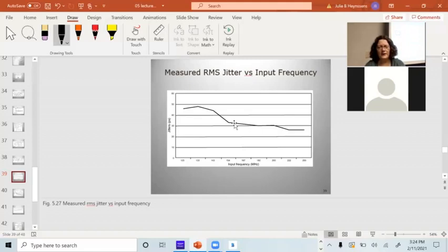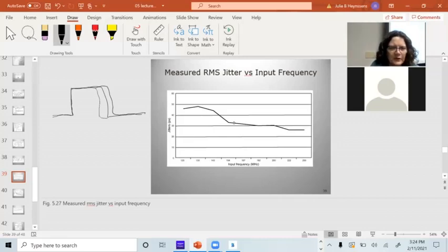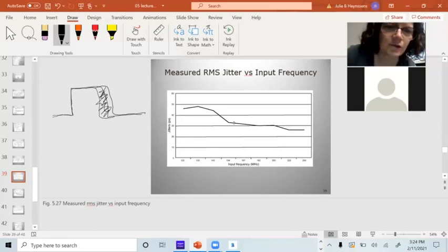Jitter is basically, you have a clock. It's better to do this with a picture. Sometimes the clock goes like this, and if you trigger your scope on your clock edge, so it always comes up here, what you find is that the next clock edge happens a little bit later. Sometimes it happens a little bit earlier, and there's a whole range of possibilities within there. And that's what engineers call jitter. It's like thermal instability inside the system causing the delays to change. The current is changing a little bit with time, and all these things affect the jitter.